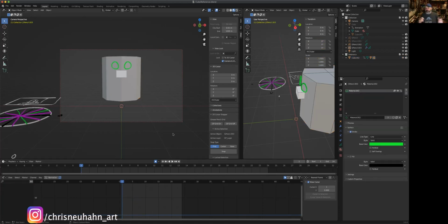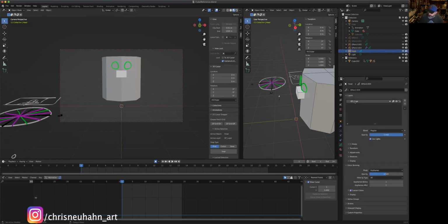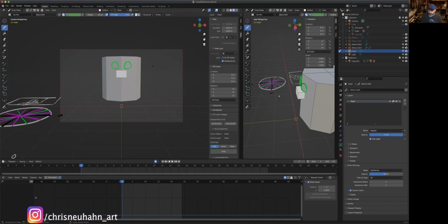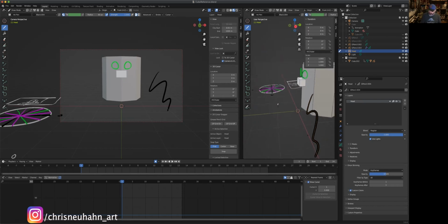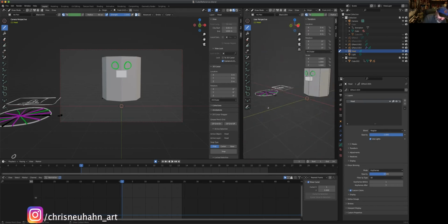So now I'm going to create my grease pencil object that's actually for my character. So Shift A, grease pencil, blank. I'm going to call this head. I want to make this layer also head. So when I draw this time, even though I'm drawing in this perspective view, I want my drawing to be flat to the world. So I'm going to change this to origin and also plane front XZ. Now anything I draw is always going to be completely flat to that view you can see here. I'm just going to draw this like it's one of my characters, my sausage looking characters.